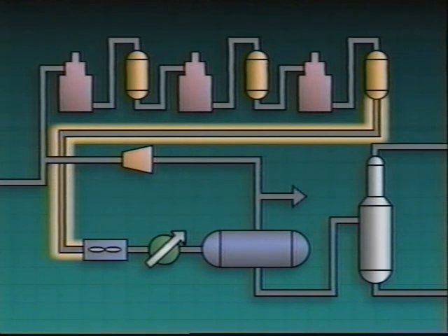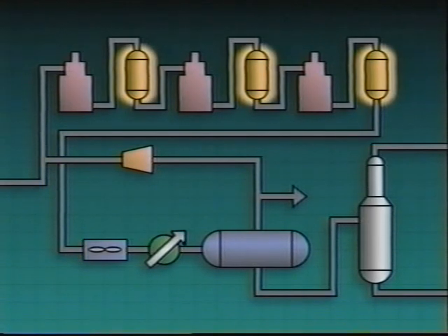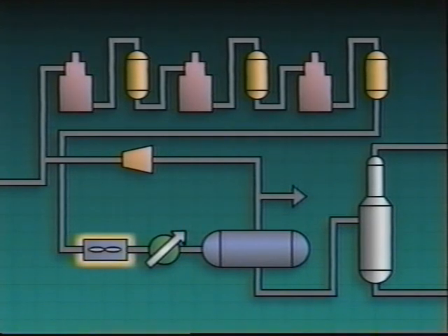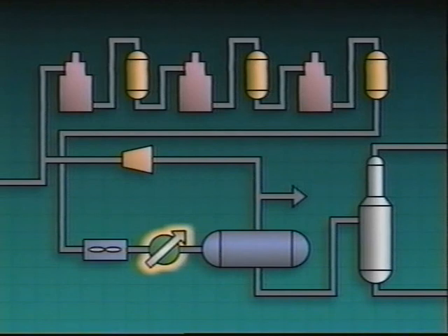The effluent from the reaction section is basically a mixture of heavy liquids, light liquids, and gases. The amount of heavy or light product in the reactor effluent is determined partly by reactor temperatures. The higher the temperature, the greater the percentage of lighter product. The lower the temperature, the greater the percentage of heavier product. This reacted product has to be condensed before it's sent to the separation section. The equipment in this section includes two condensers, a fin fan type condenser and a shell and tube type condenser.